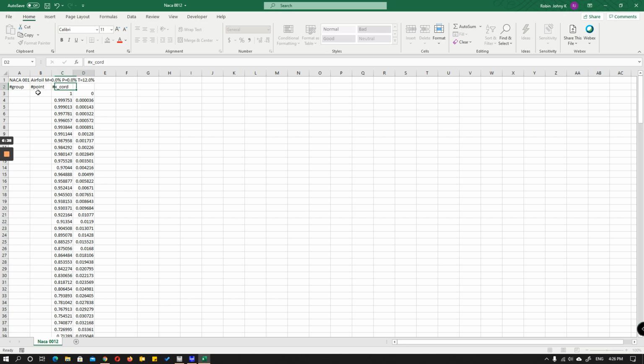Okay, here it will be the y coordinate, and then you are required to give the z coordinate because in ANSYS we are going to draw it in 3D, right? So it has to be there also, and that's all. These values you can just leave there. Z is 0, so you can just give that 0, double click here, it will become 0 everywhere.